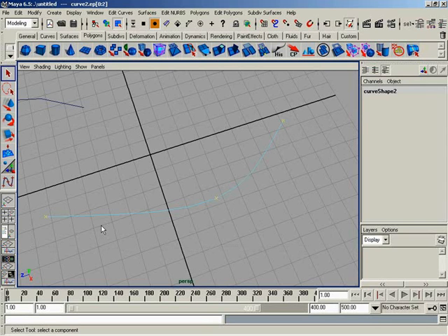Okay. Now, edit points are also referred to as knots. Anytime you see a tool setting say leave multi-knots, what it's talking about is leave 2 edit points on top of one another. And this is important later on when you get into more complex modeling and you're trying to maintain a very specific shape when you start merging curves together. If you take away multi-knots, you could end up deriving a different shape from the 2 curves that you basically merged together, if you will, or attached. And we'll talk about this a little bit later on. So that's edit points or knots.